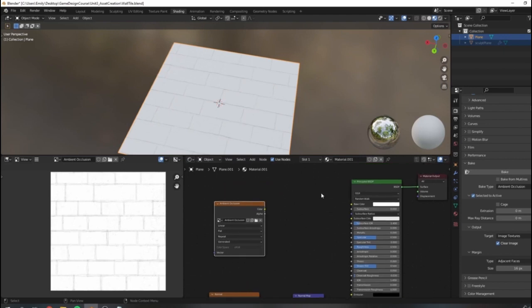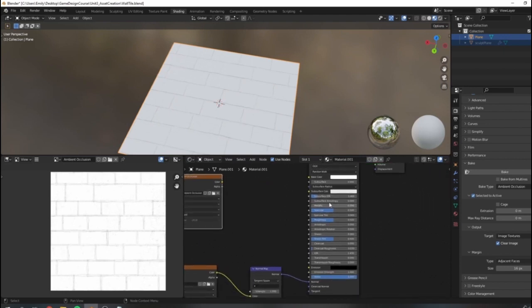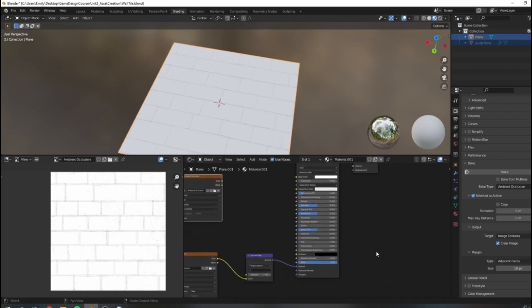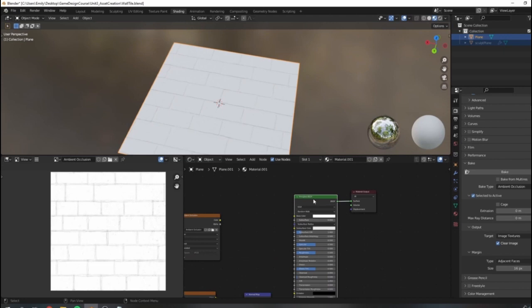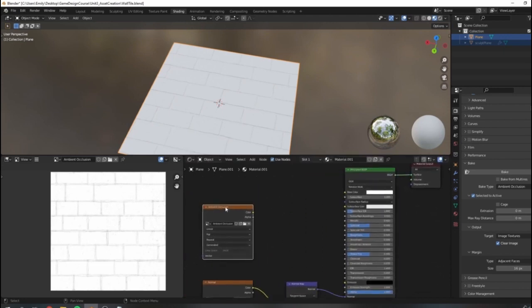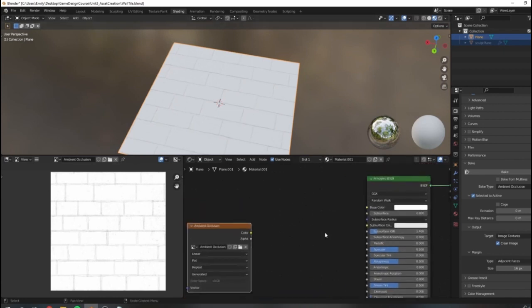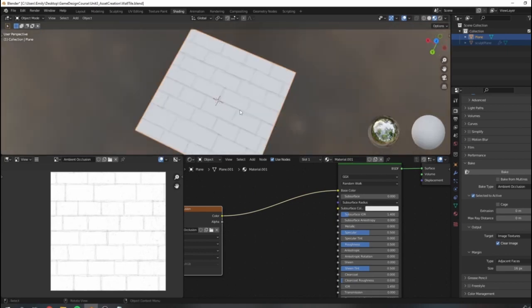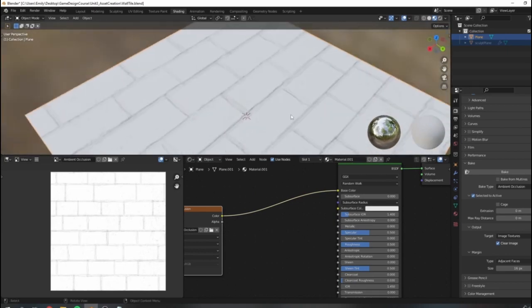to the normal map. Now, you'll notice when looking at all these options here that there is no dedicated ambient occlusion input for this type of material. But that's okay, because there's a variety of different ways you can apply ambient occlusion. If you wanted to view just this map, we could just connect the color to the base color, and that would give you a pretty good idea of what it does.